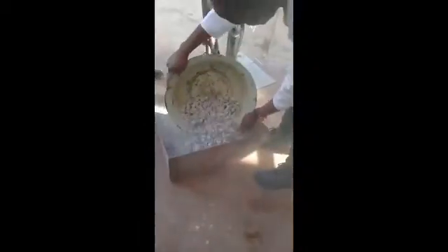The cement and the crusher sand were first mixed together in the working place before adding stone and water. After a few minutes, a little stone content was added into the cement and crusher sand mixture, with careful handling of the bowl. The mixing process was handled in such a way as to avoid segregation at the end of the practical, segregation being the separation of coarse or fine aggregates from the concrete mass. The remaining stone content was then added to the mix, and this was to ensure that the mixture is perfect.